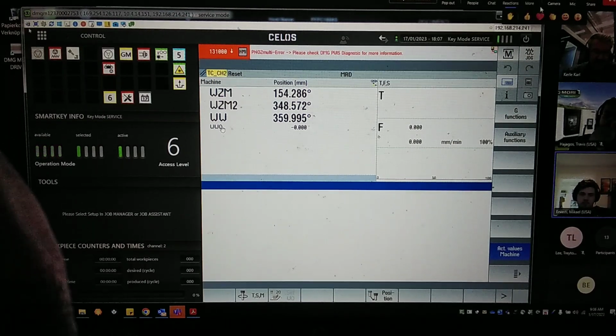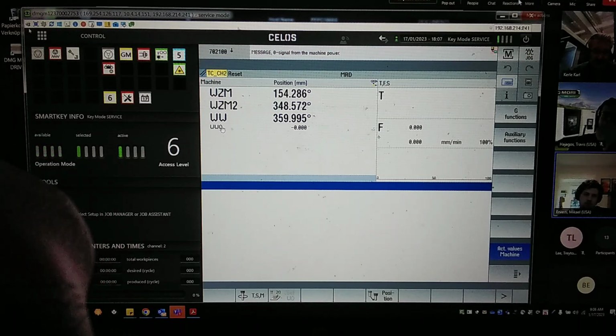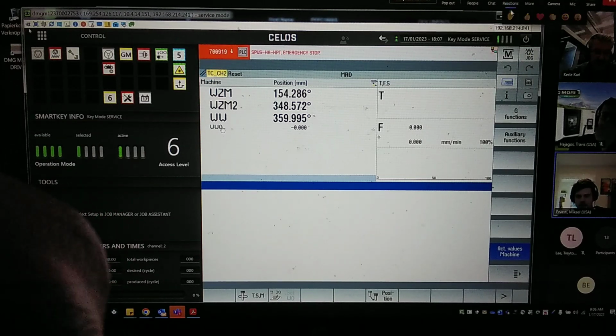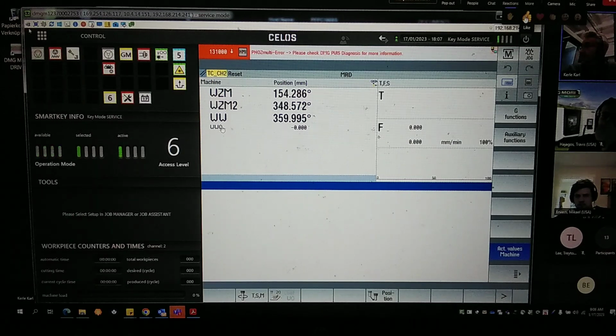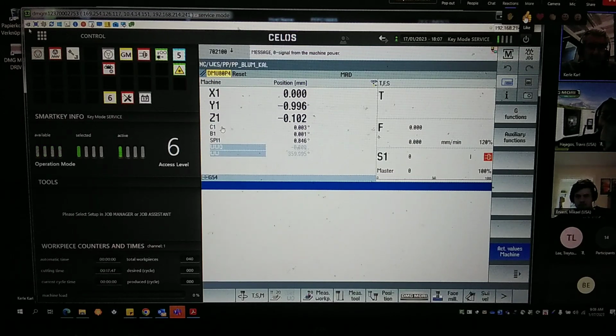Good question. Can you jog on this channel, can you jog from this area? Yeah, sure. When I press the channel button again, we are back at the standard channel 1. Channel 2 is what I'm talking about. Yes, you can jog. Correct, you are right. Here we have only 2 channels configured. The third channel is not configured by parameter, so therefore I cannot indicate it. It's not present for the control system at the moment, okay?